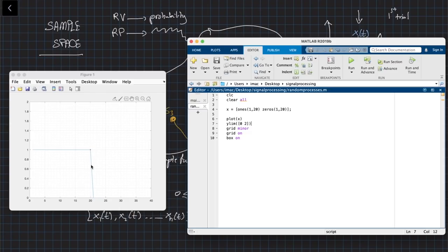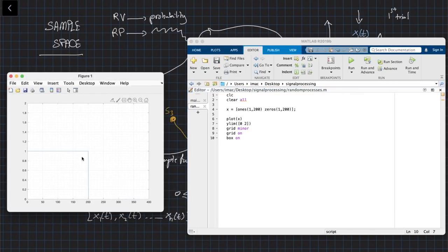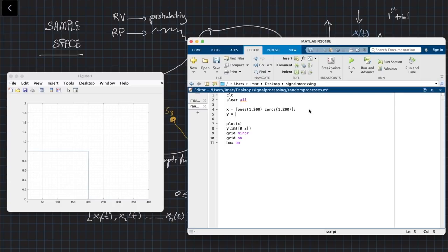You can see here it's not a sharp descending, it's not like a sharp pulse. To get a sharp one, you should increase the number of samples, so that you can have something sharp. Okay, so this is ideally the pulse that I want to send, but this is by no means achievable in a real life scenario. So instead of this X, I'm going to receive a Y plus some random noise.